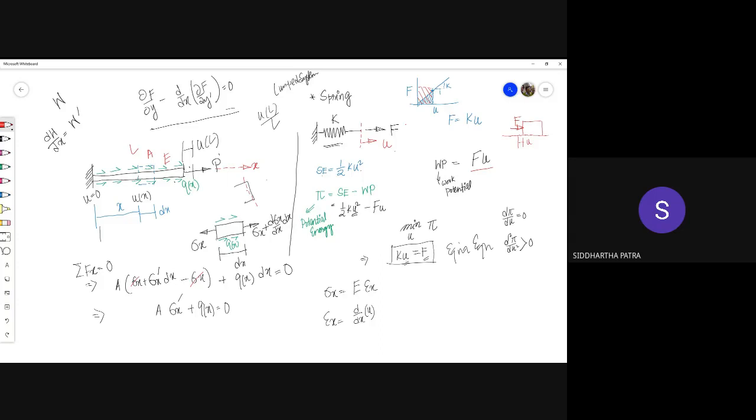By the definition of stress, the stress has to be 0. But how can the stress be zero if there is a non-zero strain? The answer is the strain is actually zero at the free end, if there is no concentrated force. It is just that it is not zero everywhere.